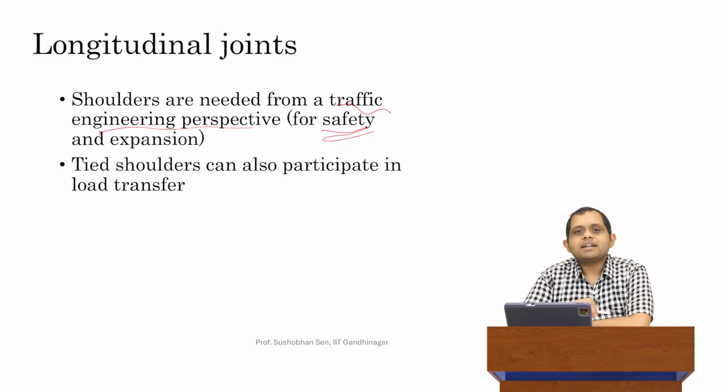Transportation economics tells us that when you build a road, generally the land prices around that road are going to increase over time due to increased economic activity. And that's essentially been the case all over the world wherever there is decent economic activity. So the idea of having shoulders is, instead of building just a 4-lane highway, create shoulders. The shoulders act as emergency stop-off, but they also allow for future expansion. You could potentially convert the shoulders in the future into new travel lanes, but the cost for acquiring the land is borne today when the land price is still relatively low. So those are two reasons, safety and economics, why we have shoulders in the first place.